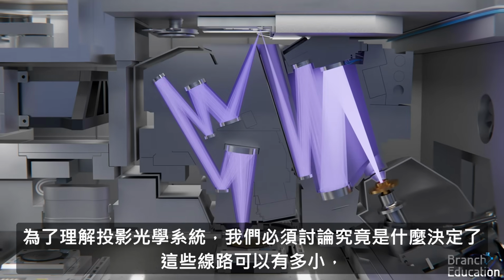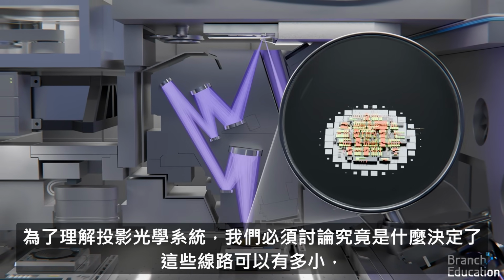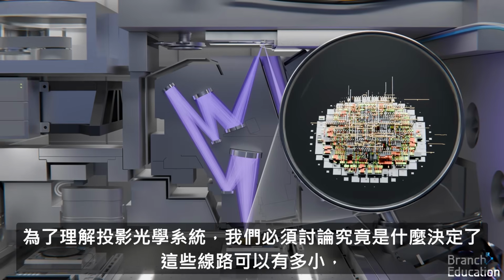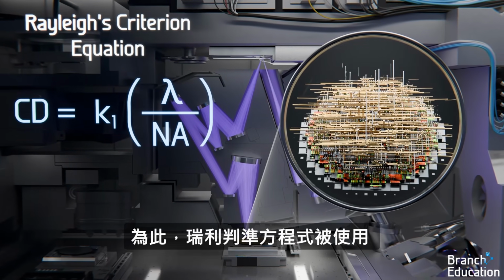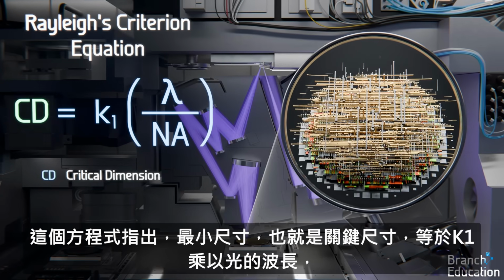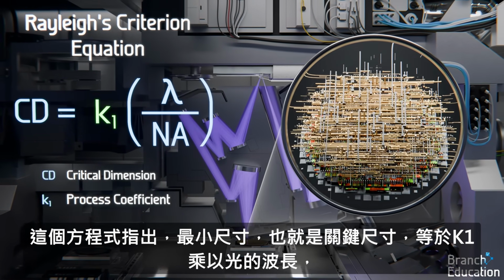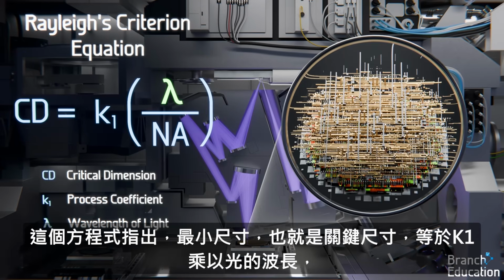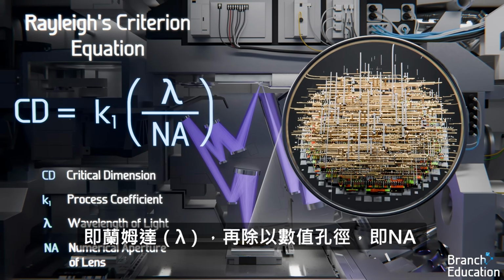To understand the projection optics, we have to discuss what determines exactly how small these wires can be, and for this, Rayleigh's criterion equation is used. This equation states that the smallest dimension, or critical dimension, is equal to k1 times the wavelength of light, or lambda, divided by the numerical aperture, or NA.